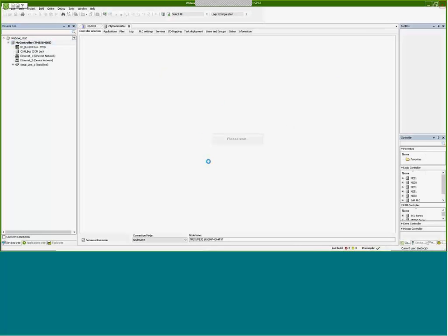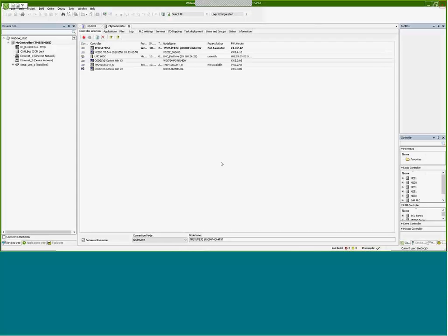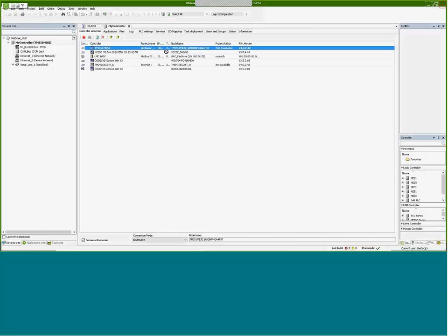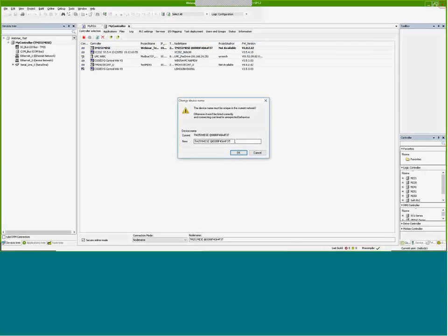So now I'm scanning all my network. And I'm going to pick here. This is the one that I'm going to talk to you about. It has my project called Webinar Test, my M251, and here it shows the node name of that PLC. So I'm going to need that information. So let me go here and copy this, so I don't have to memorize and type all that.